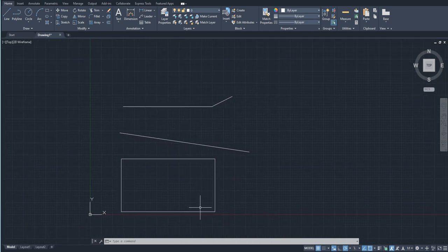As I just entered these lines, as I just made these lines by entering some units, you didn't know what these units were: millimeters, feet, inches, whatever. I'm going to tell you how to edit units. Now before that, let me just make it very, very clear that whenever you make an AutoCAD drawing, just try to make it at a scale of 1:1. You only have to scale it while plotting it. You can scale the drawing while you plot it.